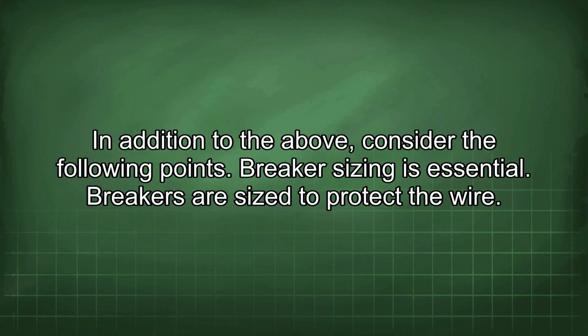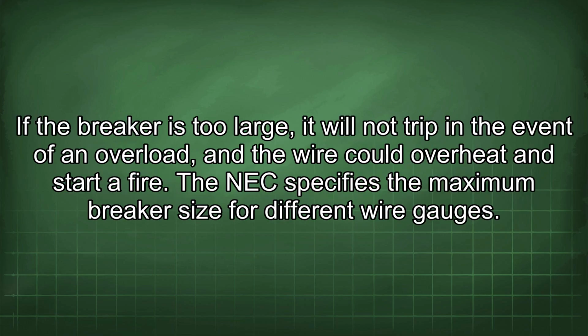In addition to the above, consider the following points. Breaker sizing is essential. Breakers are sized to protect the wire. If the breaker is too large, it will not trip in the event of an overload, and the wire could overheat and start a fire. The NEC specifies the maximum breaker size for different wire gauges.